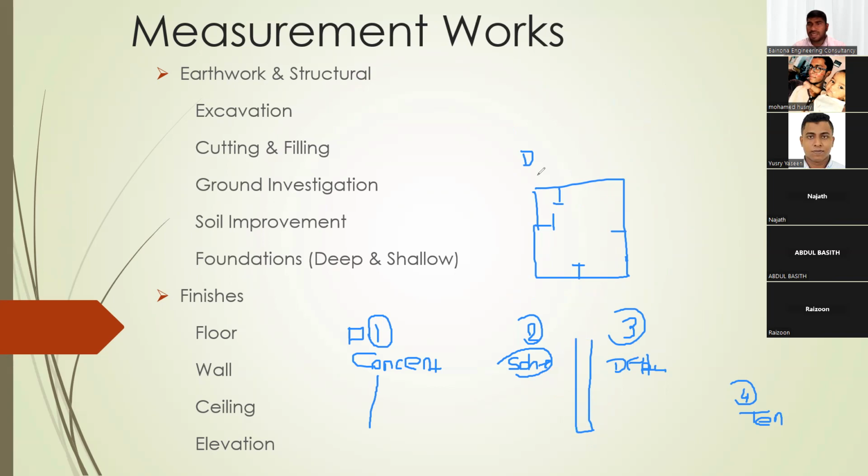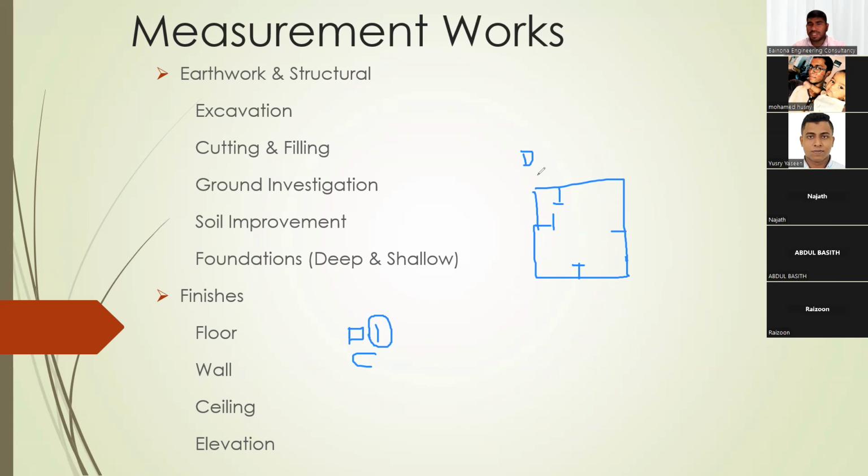But if it is less, I didn't explain to you guys how to administrate this PC rate. Let me tell you how to administrate it. When there is a PC rate in the BOQ, when it comes to the project stage, you see 40 dirham PC rate in the BOQ. So client will tell the contractor to bring the quotation for the 40 dirham, or he may have a quotation from his people.